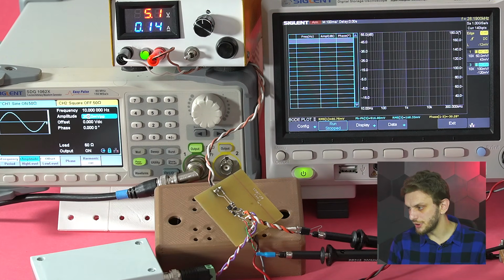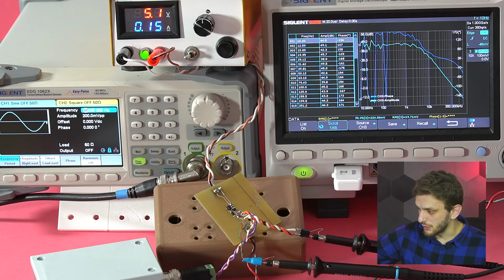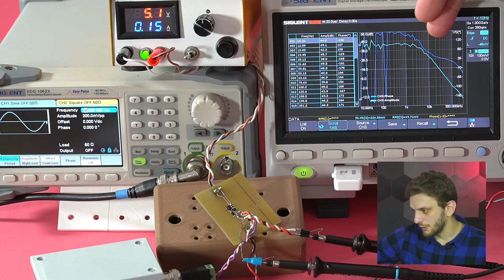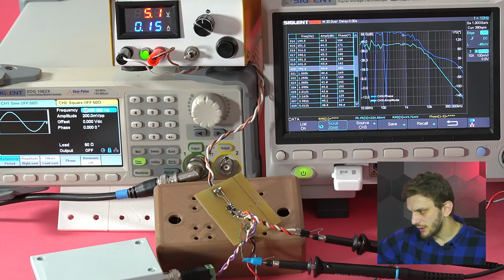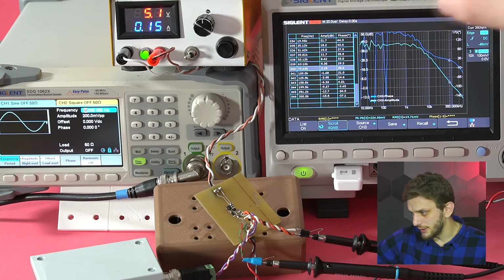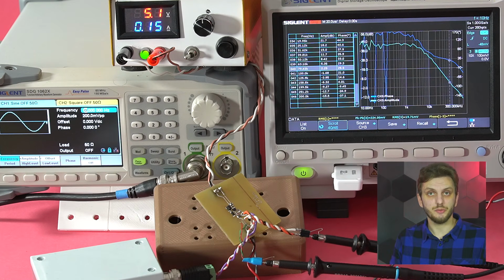And if we run the measurement and wait for it to finish, we can have a look at our Bode plot. So we can see a relatively flat gain plateau going up to a certain frequency, after which it drops off. So we start with about 40 something decibels, and then our crossover point, where our gain reaches the value of 1, is somewhere between 80 and 100 kHz. Now, unfortunately, at this frequency, we have a very small phase margin, so only 20 something degrees, so it's not the most stable power supply.